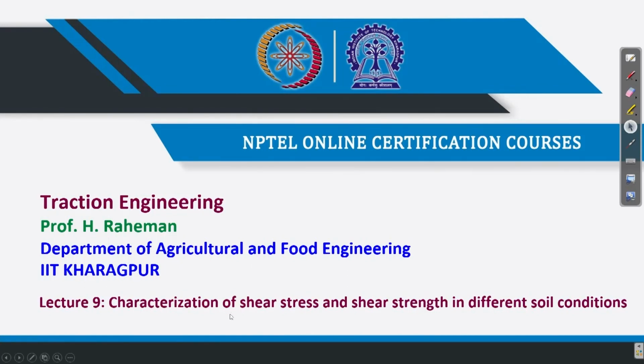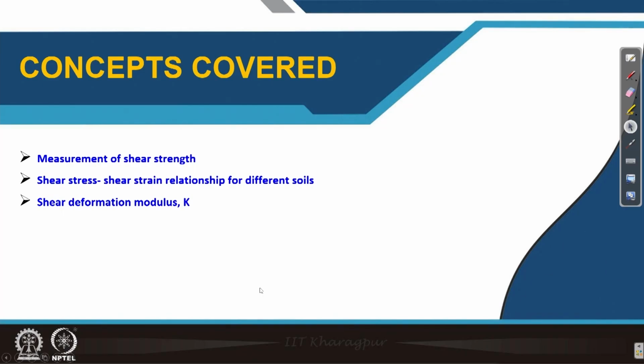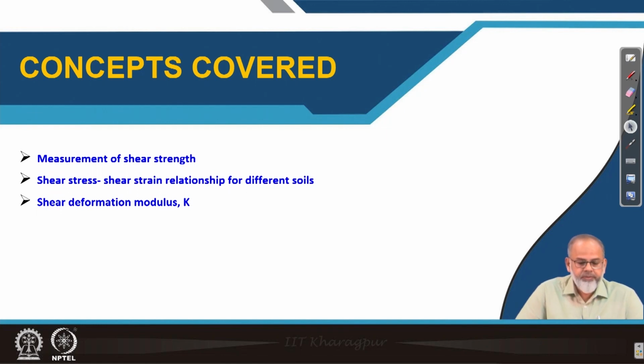As the shear stress is important in deciding the tractive force which is developed, that's why we are going to take up this lecture, where the concepts to be covered are measurement of shear strength, how you are going to measure the shear strength of soil, then shear stress, shear strain relationship for different soils, then how to find out deformation modulus K.